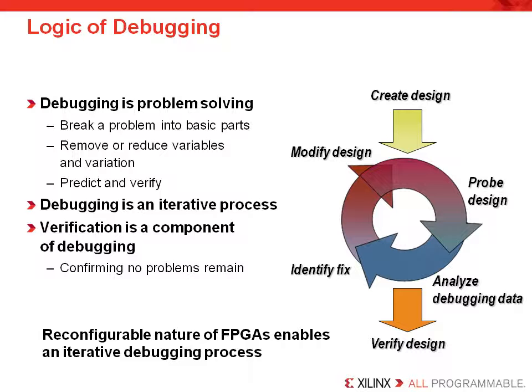Electronic debugging involves probing a design to determine what is happening on the chip at the die level. To do this, the ChipScope cores are placed in the FPGA and can be connected to the nodes the user wants to test. This enables a user to test portions of a design independently. Then verify the design's functionality in an iterative fashion, so the user can break the design down into several major components, test the various input and output signals of each component, and finally decide about making any design changes.